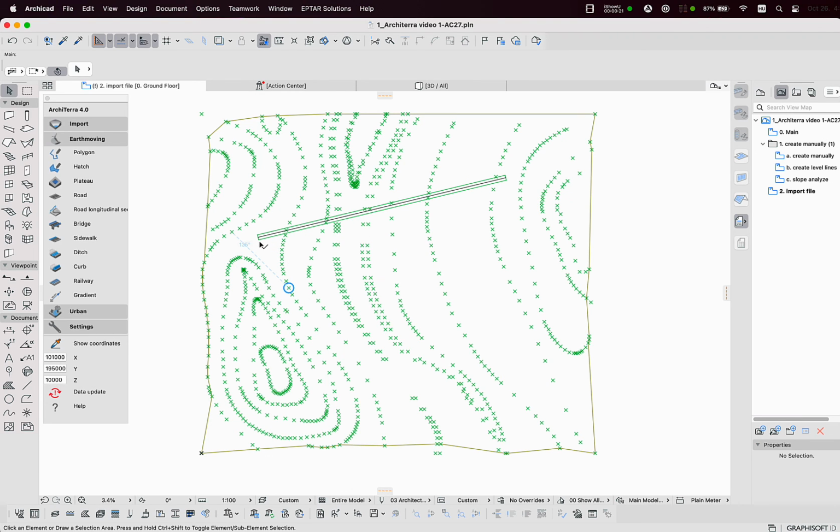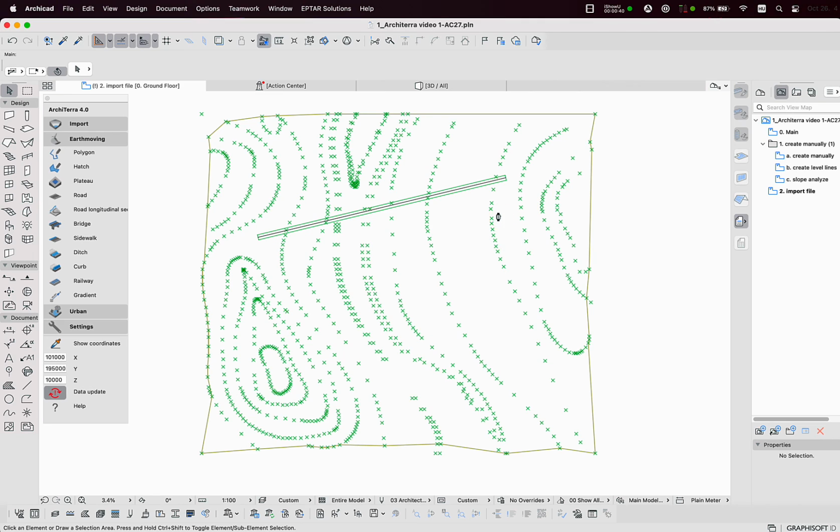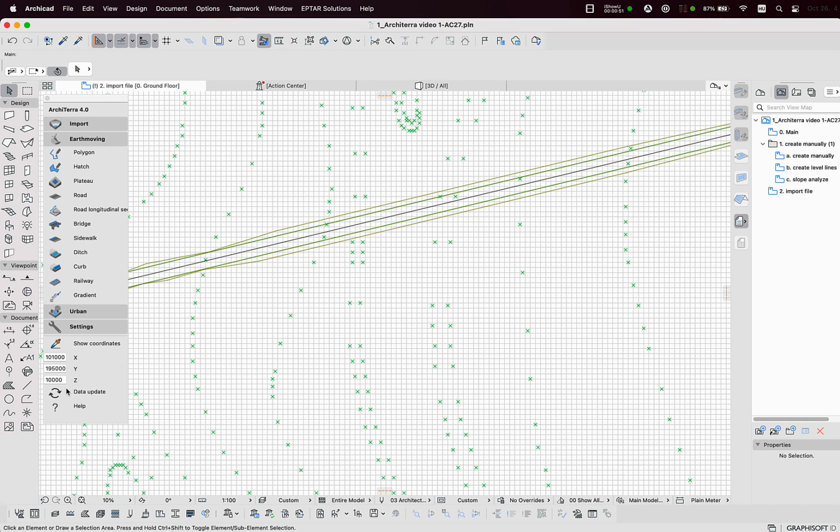During the work we can do many changes in the terrain shape and surface, and it is not always visible immediately. To update the terrain, I can click on the double circular arrow icon and refresh it. If there were any changes done in the terrain, this icon switches to the red color with an exclamation mark, so I can see that the terrain should be updated for correct representation. When there are no changes, this icon is simply black without any warning signs.